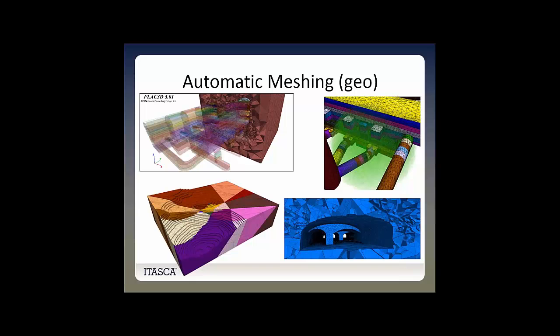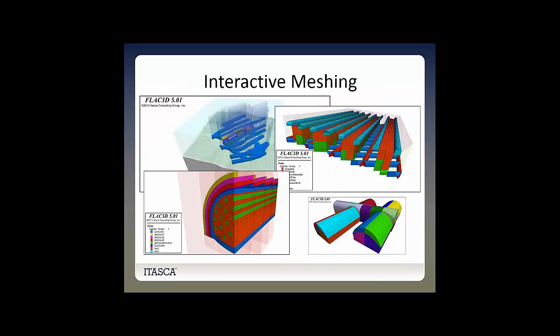You simply have a number of opportunities in terms of global quantities, what global density you like, what global type of element you like, etc., and the mesh is produced accordingly. So automation means to some extent less control, certainly less local control. Interactivity, on the other hand, means much control, less automation, more tediousness, etc.